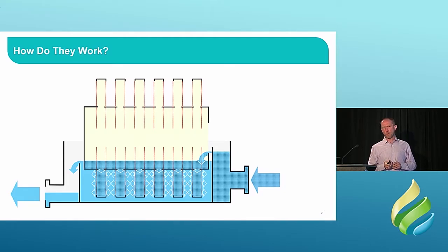The reason for the weir and holding back some water, there's really two reasons. One is to do with hydraulics, and the other is to give you a stored volume, a reservoir of filtered water, because that's what's used for backwashing. So you can imagine over time, those particles are building up on that filter cloth in each of those discs.